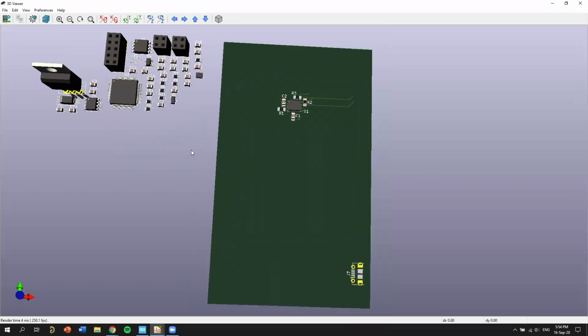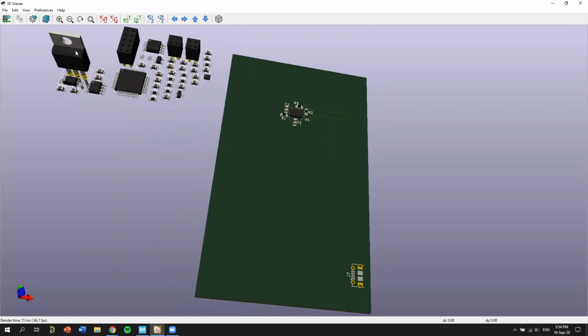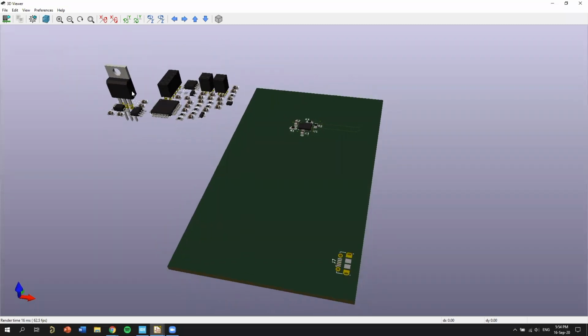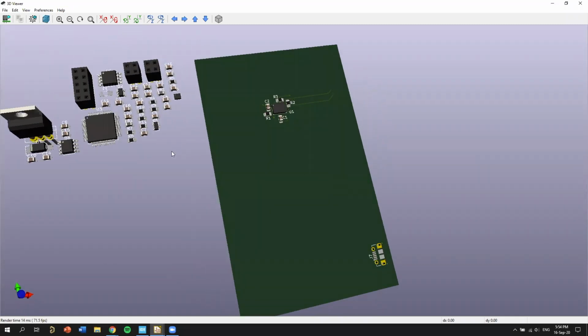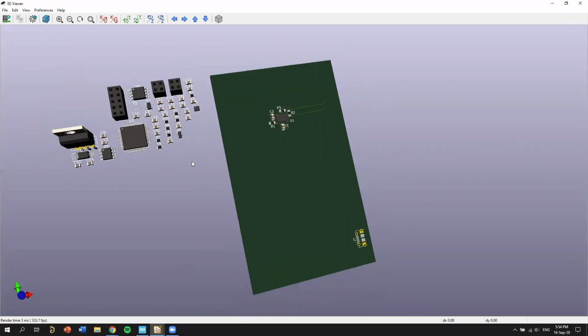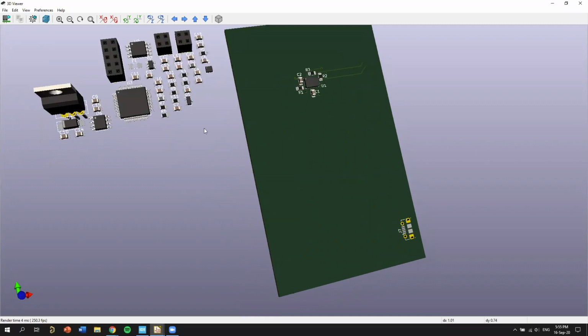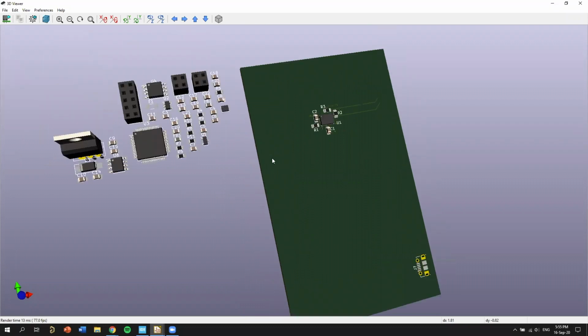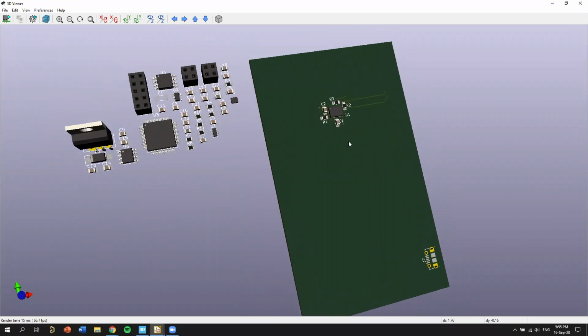Cool. All right. Obviously I chose the wrong one. This big transistor here is not the package that we want. We want everything surface mount. So the task is to put all of this on their respective spots on the board, figure out nice placement so that everything works together and they're easy to route.